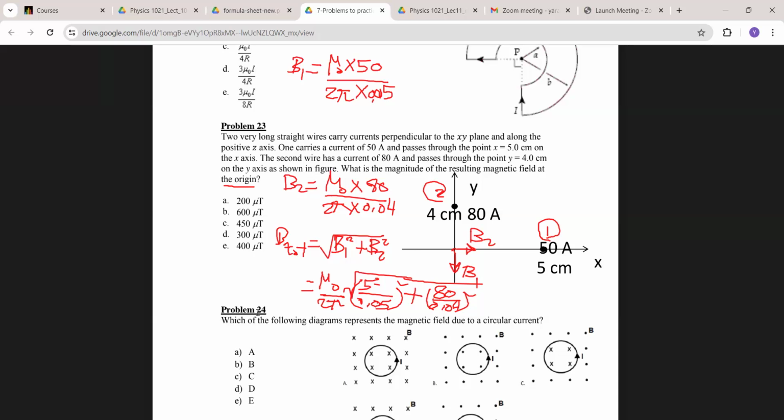From here, this is 5 million, square root is 2236, multiplied by mu naught, which is 4 pi times 10 to the power minus 7, over 2 pi. So it would be multiplied by 2 times 10 to the power minus 7, giving 447 micro Tesla. So the closest answer is C.